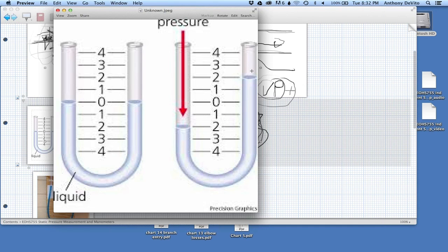So now if we connect one end of this, like for instance the right end, to the suction side of the ductwork, right up against the edge of the ductwork, so we're not actually blowing into this tube, the air is passing over it. We're not blowing into it, which would also measure some of the velocity pressure. Just on the side of the ductwork, we'd measure the suction that the ductwork has, and the levels would change. The stronger the suction is, the further it would pull this water up into the ductwork. So the difference in the height of these two represents how much suction we have.